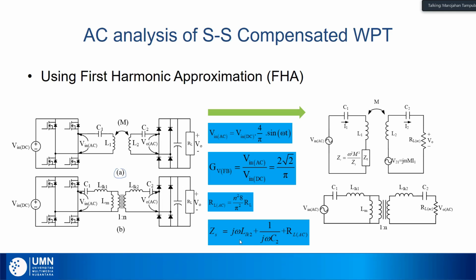And then if we want to find all the impedance in the secondary, we can use these equations. And of course, these equations only work in series compensated WPT. If we use another type like series parallel, or LCC, or LCC-S, or double LCC, of course we will have a different model.